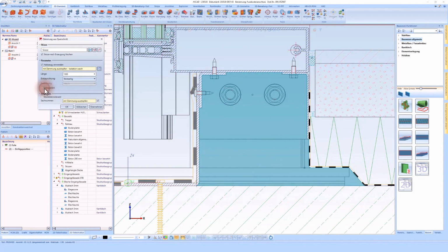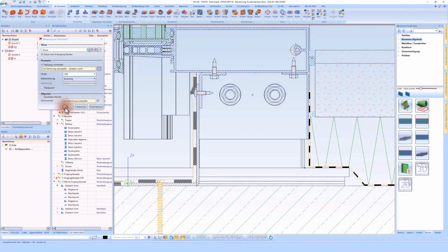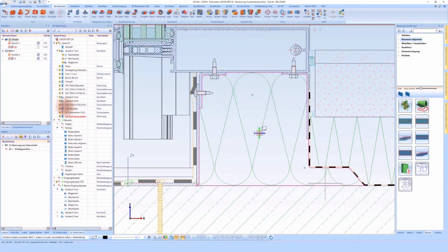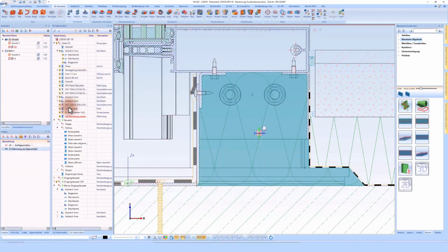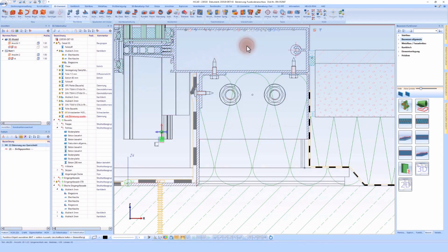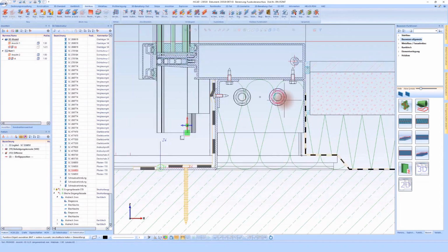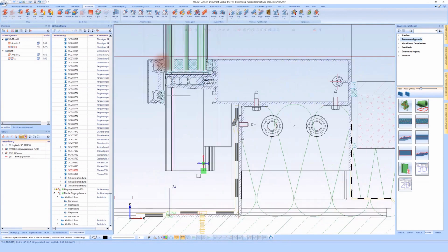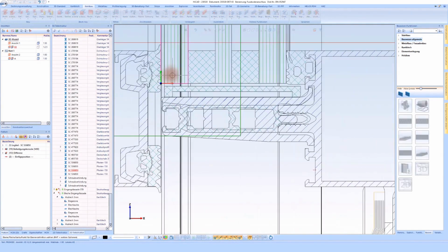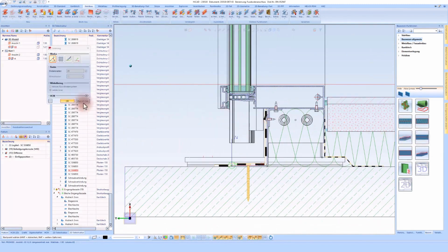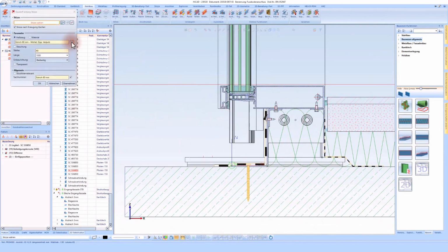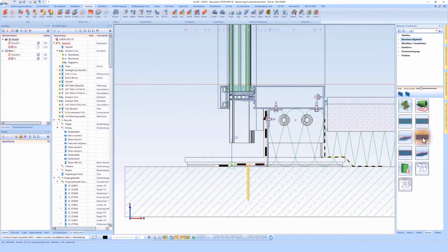In this case, I consciously say completely transparent because I want to leave it out in the first step so that it looks the same. Transparent means that in this case it would cover the other screws and everything behind it, which I do not want. So I click again, double click, and say, in this case it should be completely transparent, meaning that the rear parts will also be displayed.